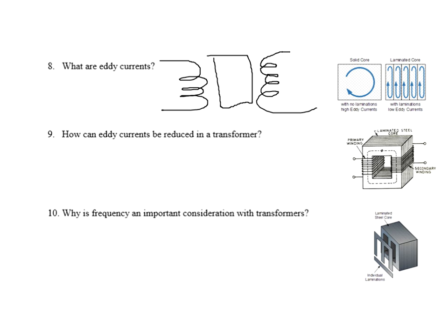The lines of flux that are circling here cut through this core on its way to the inductor. You will generate current in there, and inside of that core is current flowing. The problem with that is it reduces the efficiency. The voltage and current that should be going on here, you lose some of it in the core. And they have a name for those. The term of endearment for the currents that develop inside of a metal core, and every metal core has it, they're called eddy currents.